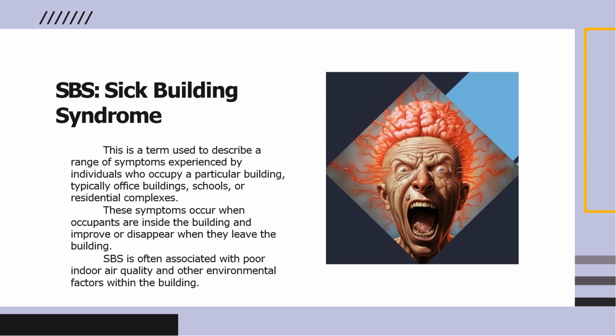SBS, sick building syndrome. One way to look at sick building syndrome is where you have more quantity of carbon dioxide in the air than the acceptable limits in natural air. So with these uncomfortable levels of CO2, it's possible that people will begin to have sensations or it will affect people's performance in a workplace. So SBS has to do with the air quality as well.